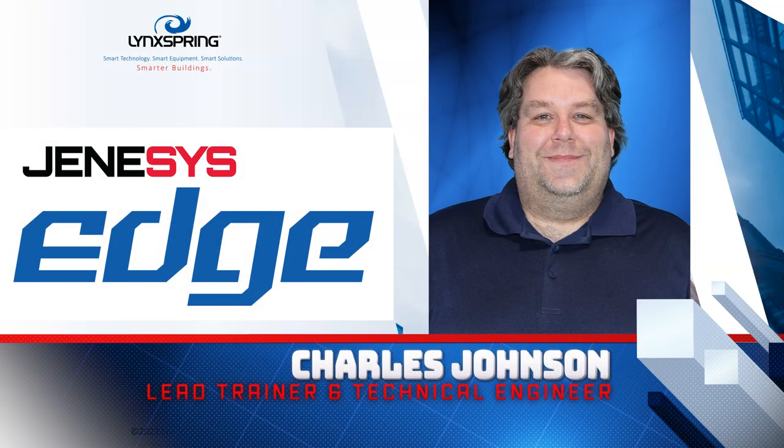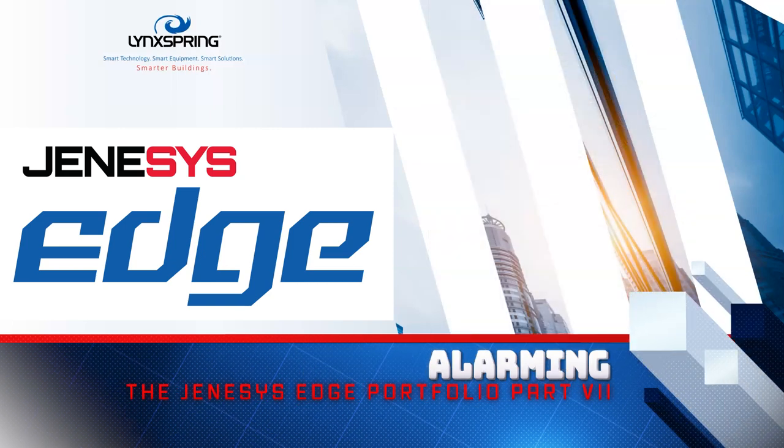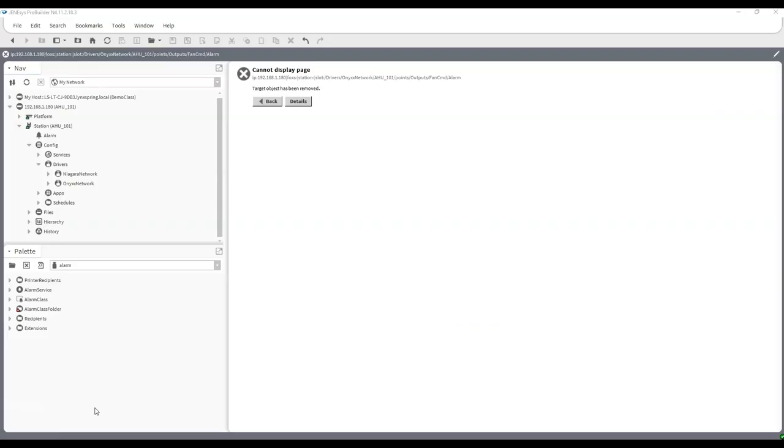I am the lead trainer slash technical engineer at Lynxspring, and today we're going to be talking about alarming. So what is alarming? Well, alarming is the process of enunciating when an anomaly occurs. So something is off. A point can go into alarm or fault. If it goes into alarm, the value is still valid and is used in the system. And when the point goes into fault, it is no longer considered valid and is ignored in the system.